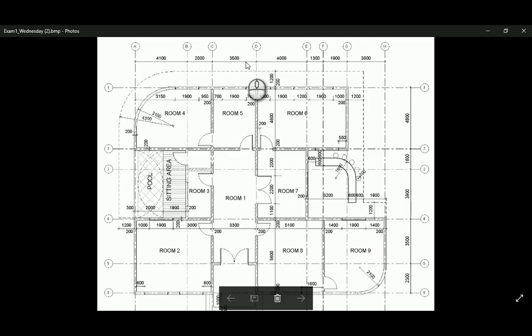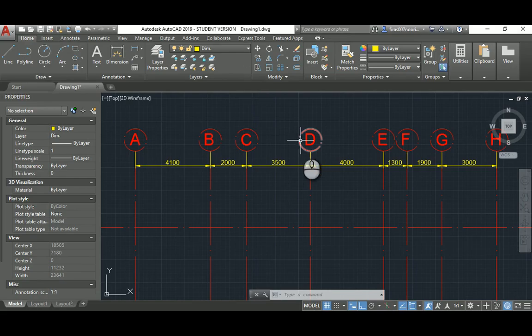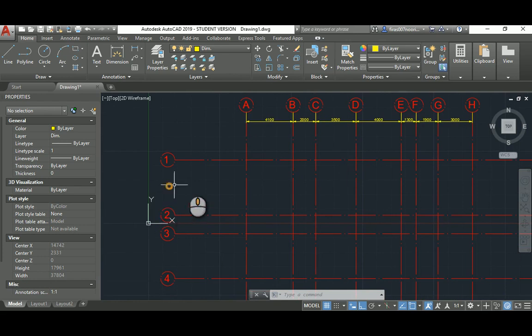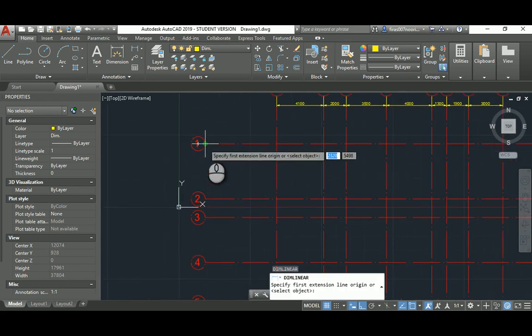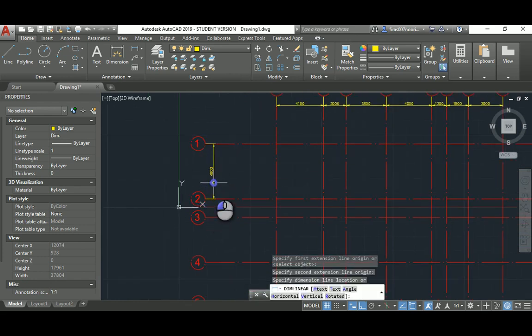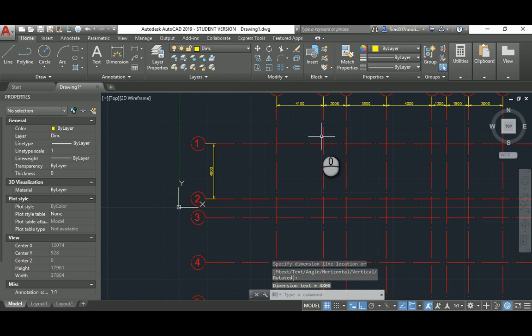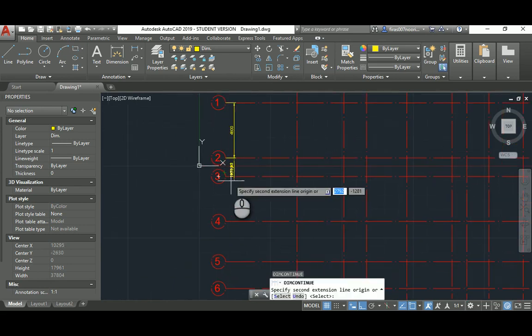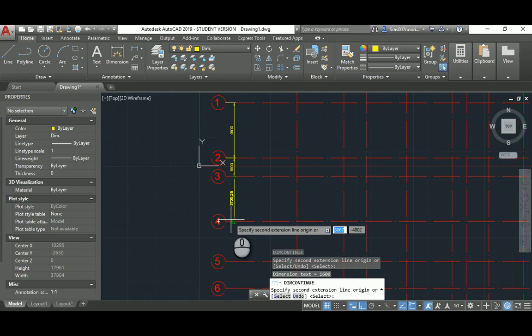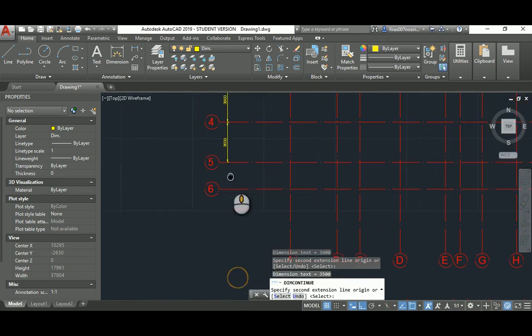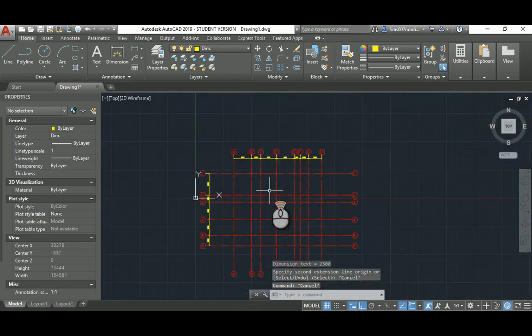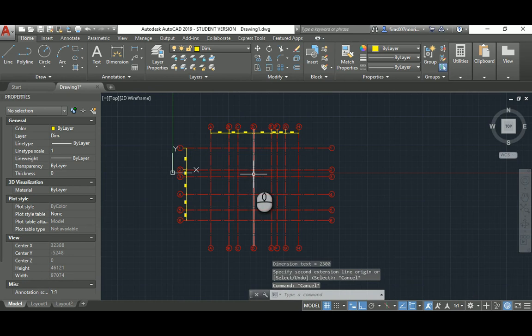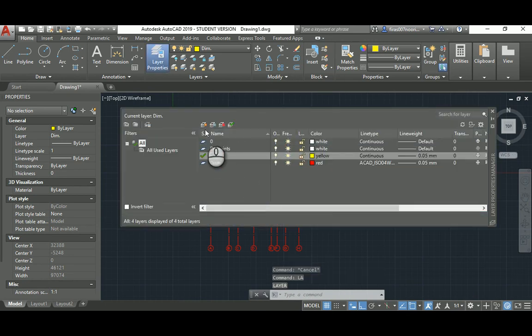Make sure that they are right, and if you need to fix, you can fix now in a couple of seconds. Better, you know, when you go advanced and make lots of walls and dimension and hatch, it will be much harder to be fixed later on. So that's what we want for now. So layer again, and this time create the walls.